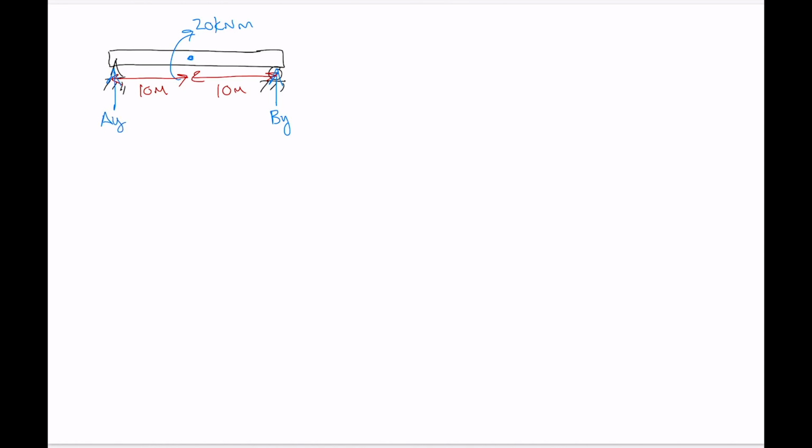Okay, so let's draw the shear and moment diagrams for this beam. So first things first, let's get our axes set up. Shear in units of kilonewtons is looking like it would be sensible from the loads given on the free body diagram. Moment in units of kilonewton meters.